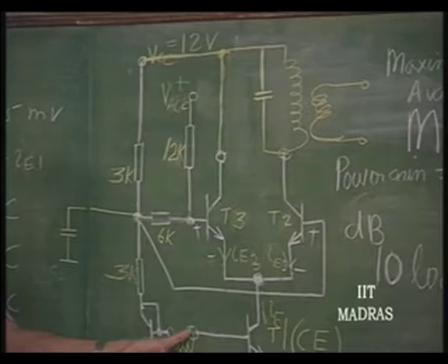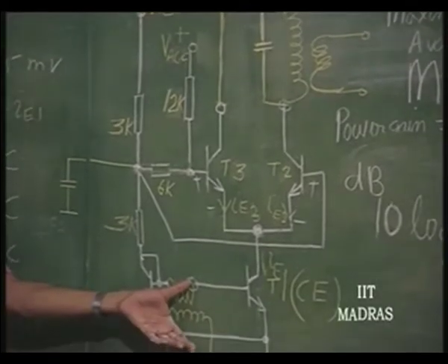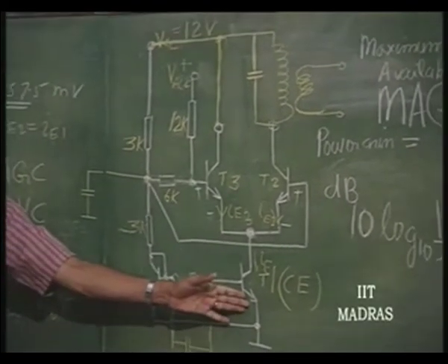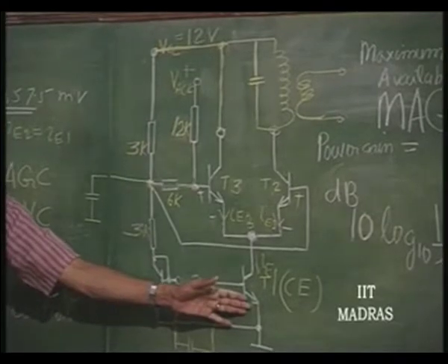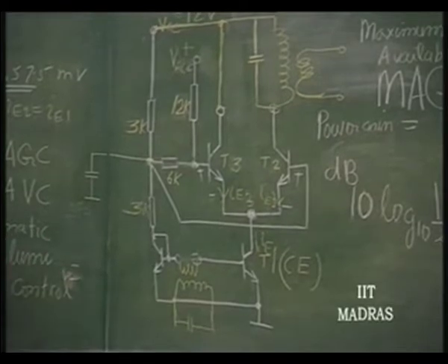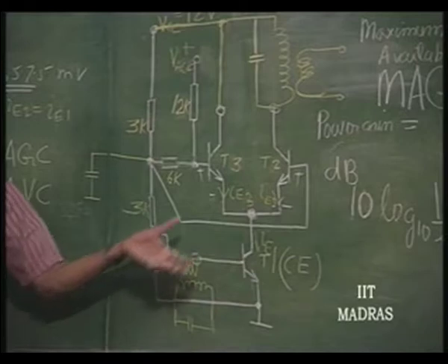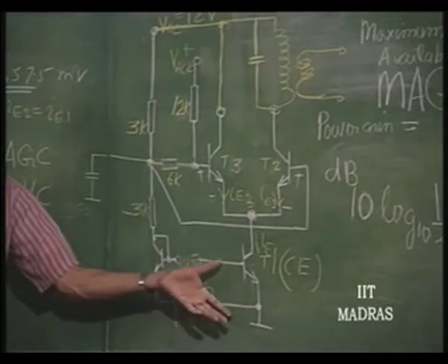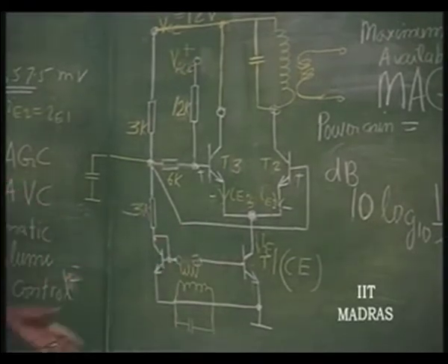So, that your parameters y11 and y21 do not vary, because this current remains constant. In a regular cascode structure without this arrangement, these parameters vary and this gain also varies, because AGC is necessary, this current varies in order to vary the gain, then automatically the parameters vary, detuning also gets disturbed.